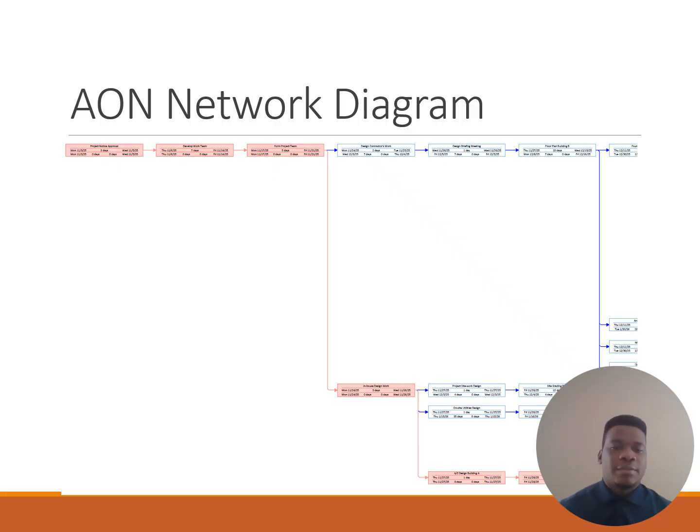These are the activities that have zero float and determine the total project duration. The blue tasks have available float and some scheduling flexibility, and this diagram serves as the basis for determining early and late start schedules. So I have about 4 slides.